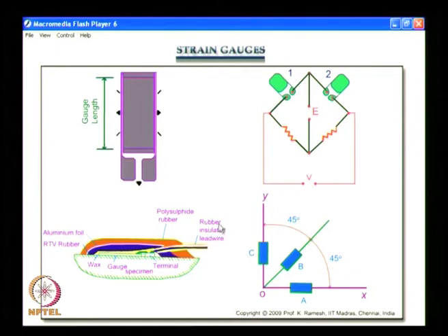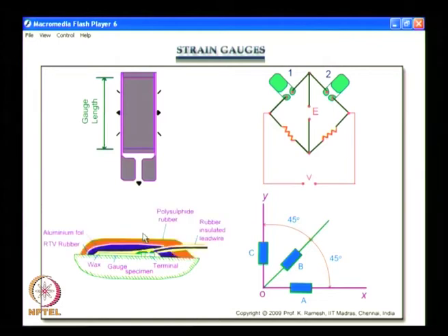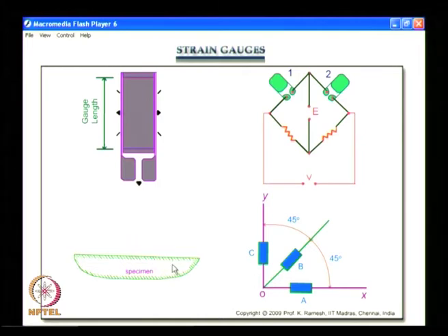Then you have how strain gauges need to be protected in aggressive environments, that is also very important. You have several layers of coating applied, particularly when you want to do it underwater, piping and anything to do with that kind of aggressive environment, you need well protected strain gauge installation.